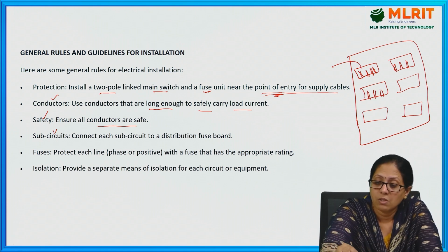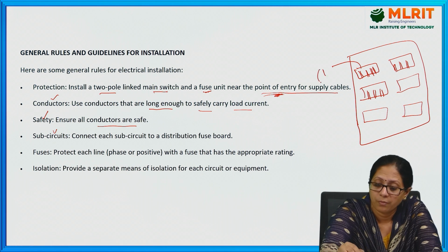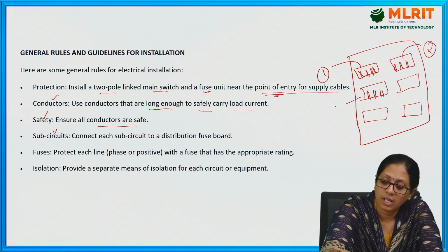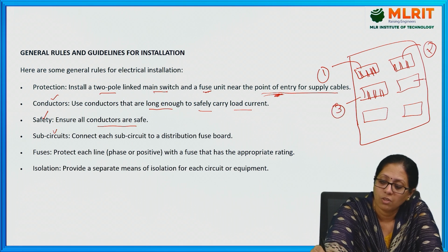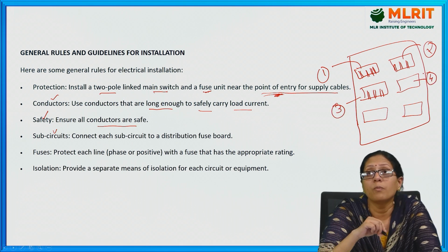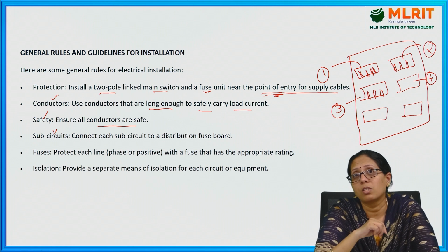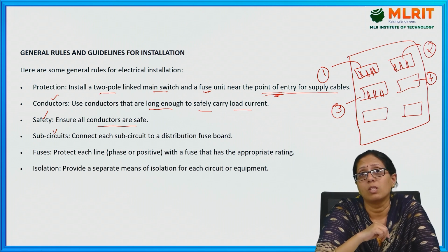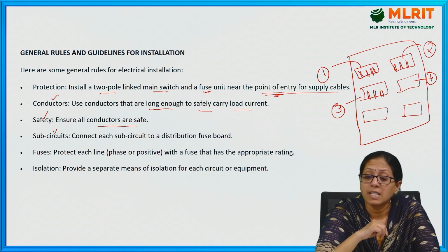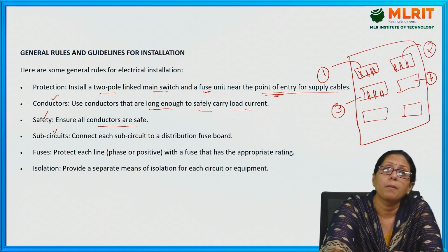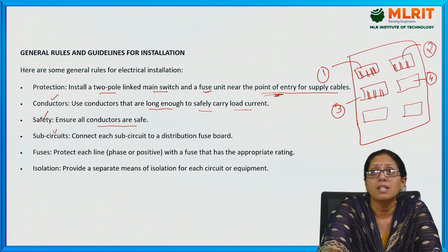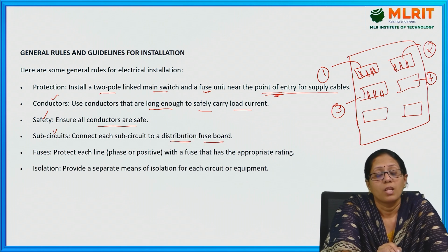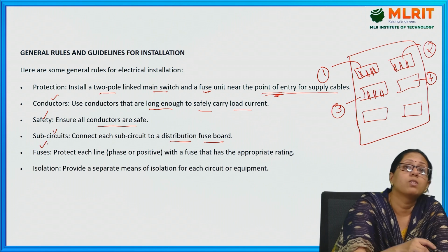You can say this one is one sub-circuit, this one the second sub-circuit, this one the third sub-circuit, the fourth sub-circuit. So different sub-circuits will have different fuses, and all these sub-circuits are placed in a single distribution fuse board.